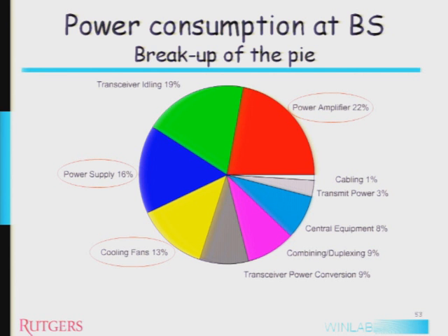Should I shut up and wait? I think so, and let me explain to you why. We are missing a whole other dimension, which is what kind of deployment are we talking about? If it's a 1 kilometer or 10 kilometer intersite, you get a very different answer than if it's 100 meters. And there's a whole debate: are we talking about these sites that exist today or the ones that may exist 10 years from now? From what I hear, 10 years from now we may be talking about 10 meters, and there it's going to be dominated by processing power consumption, not by RF, while at 2 kilometers it is dominated by RF. So it's a moving target. It's fun to discuss, but perhaps unfair to China.